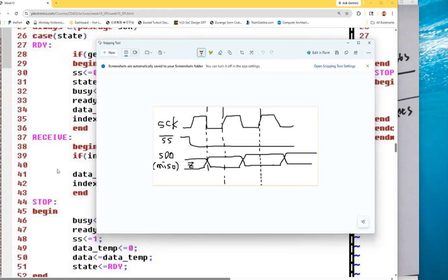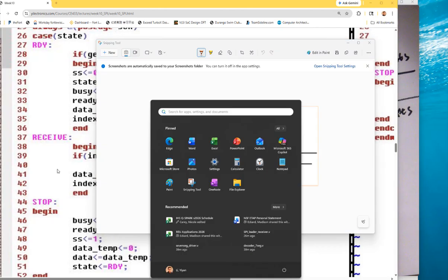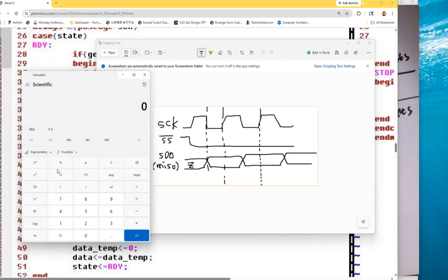All right. One more last thing for question number 8. We answered the first half already, and for the second half, what is the sampling rate of the SPI? You are thinking, hey, SCK is running at 2 megahertz and takes 16 SCK cycles to finish one sample. So you are thinking the samples per second seems to be 2 megahertz divided by 16. So you are expecting 125,000 samples per second, and that is not right.